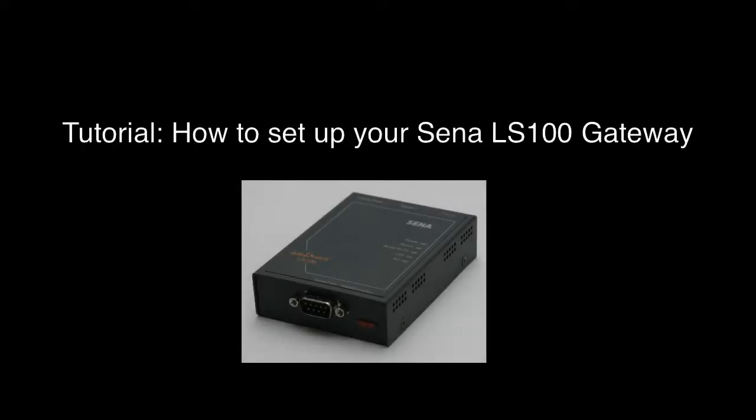Welcome. In this tutorial, we will be covering the process of getting your Sena LS100 gateway configured to communicate with the Zone Beacon application and your Centralite Elegance MCP. Just as a forewarning, I will be doing all of this on a Windows-based PC using a terminal program to communicate with Sena's LS100 gateway.